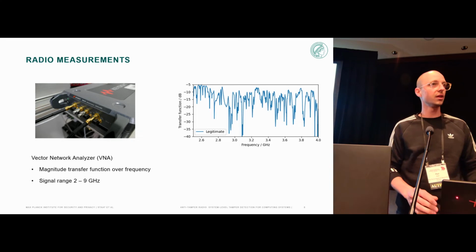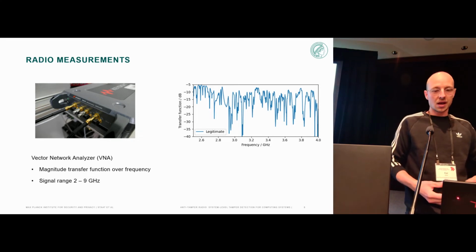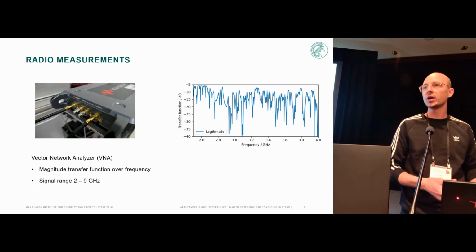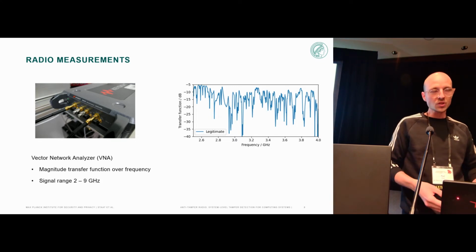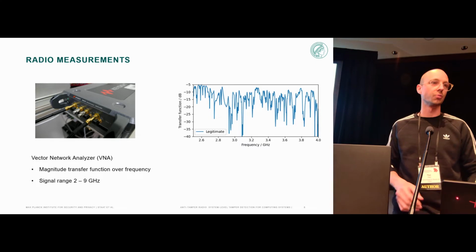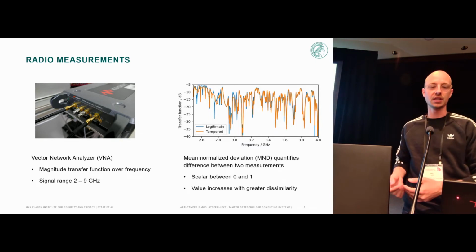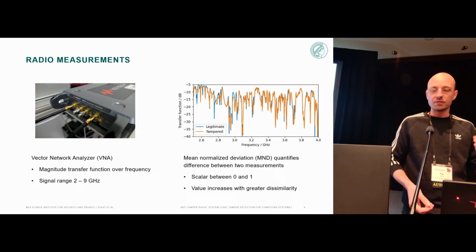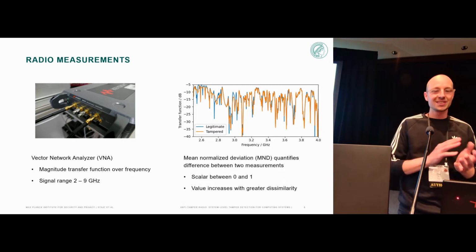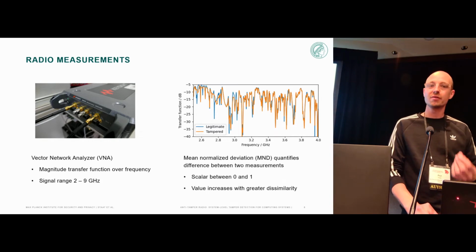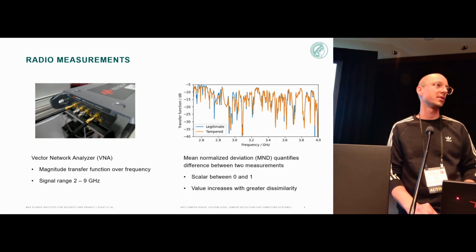It shows how much the transmitted signal is attenuated over frequency due to the environment-dependent signal propagation. Now when we insert the probing needle into the environment, the transfer function will slightly change, and it is this change which we leverage here as a tamper detection mechanism.